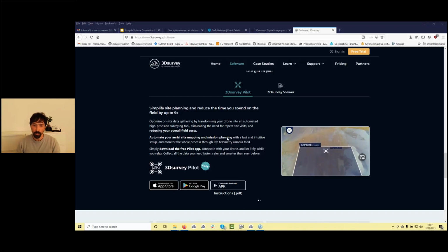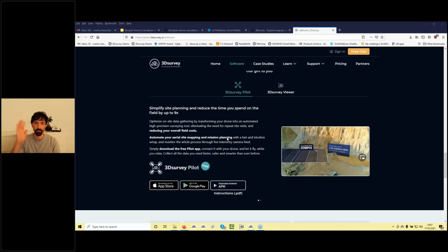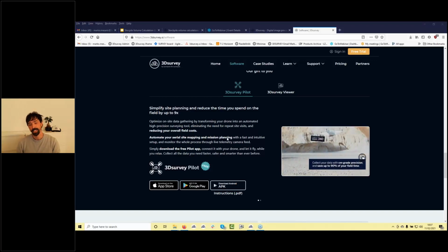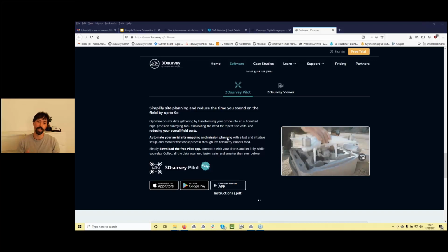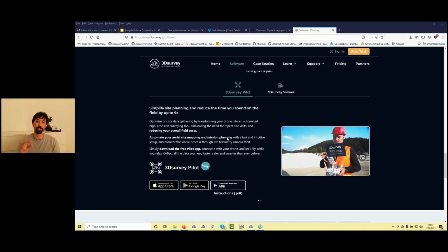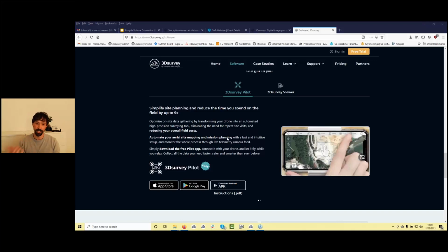We did also measure a test if the RTK works without ground control points, because I know a lot of software providers also tell you, yeah, you don't need ground control points and so on, but it's not actually true, because we did a test on the same field 10 times with the RTK, and I can say 4 times we get accuracy up to 4 centimeters, I mean 3D accuracy, and the other 6 times there was a displacement in height for 20-25 centimeters.